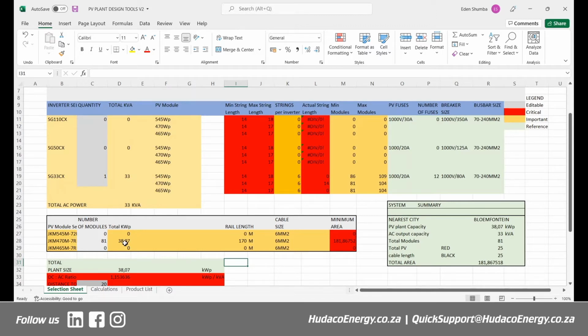And my DC to AC ratio is going to be this one here, 1.15, which I think is low, right? And here it has given me the actual string length if I use 81. So it tells me I'm still within the range, 14 panels per string, right? That is the smallest. But it allows me up to 17.